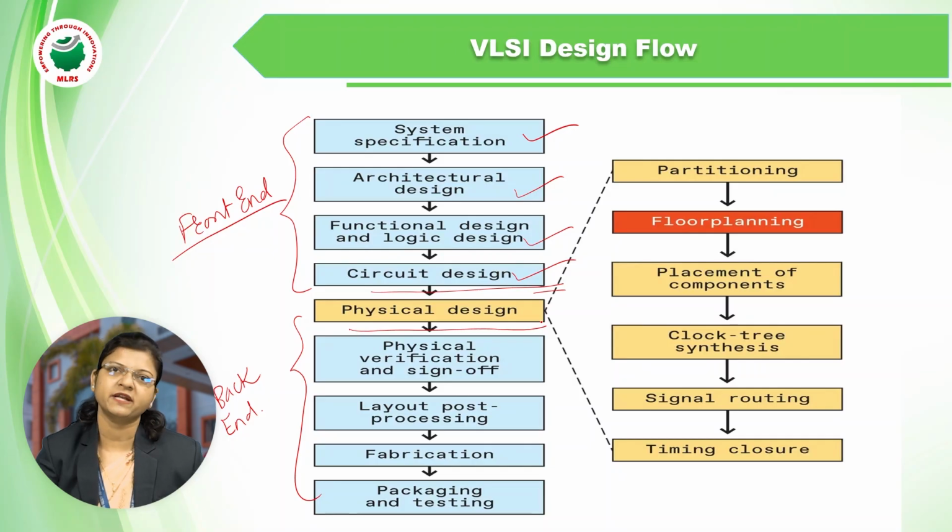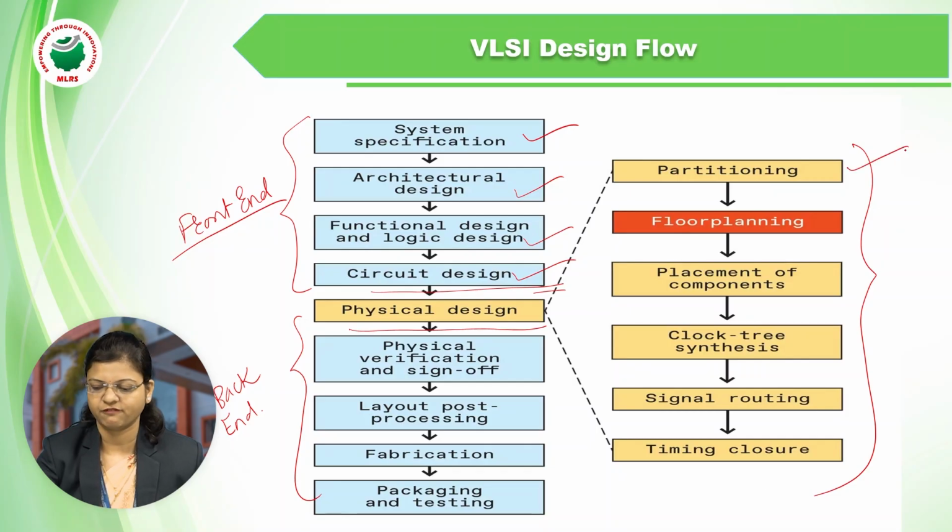But inside that physical design, we have other steps. First will be partitioning, floor planning, then placement of components, clock tree synthesis, which in short we call CTS, signal routing, and timing closure. So all these six steps are involved in the physical design.